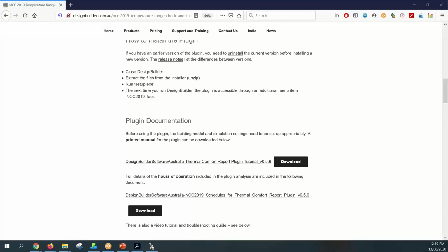How does zoning impact PMV? Is it an advantage to have more or less zones? Well, that's a pretty hard one to say. As a guide, the PMV is calculated on what's called the geometric mean of a zone. So it's probably not a good thing to have a very thin zone. It's probably good to have a zone which is at least 3.5 meters wide, and the PMV gets calculated at the center of that.